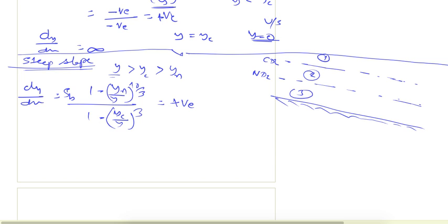So again in zone 1, as I said earlier, if a profile is occurring in zone 1, it will be a rising profile. In the downstream it will be defined by some other section which is controlling the depth of this structure here, and in the upstream it is meeting the CDL line.